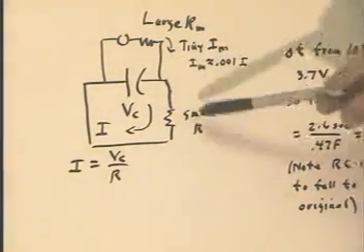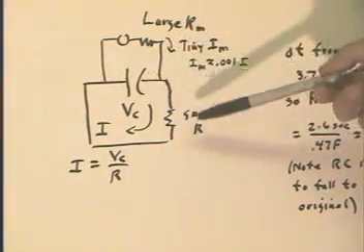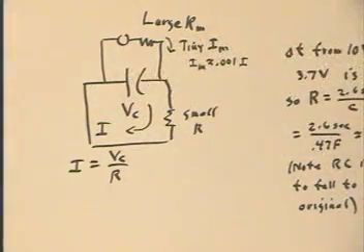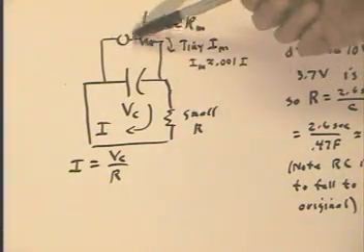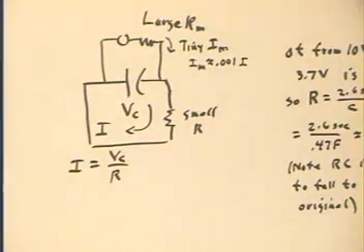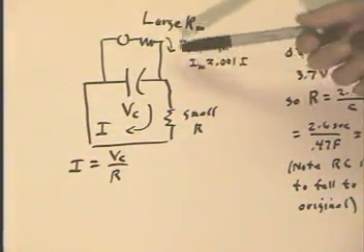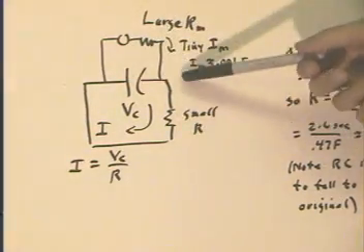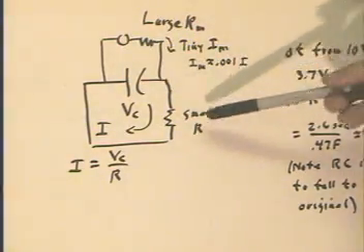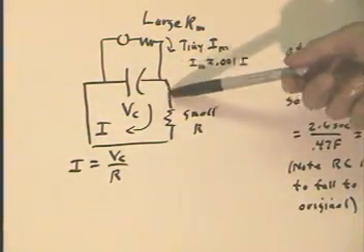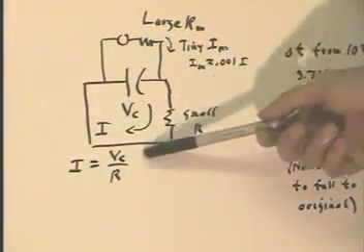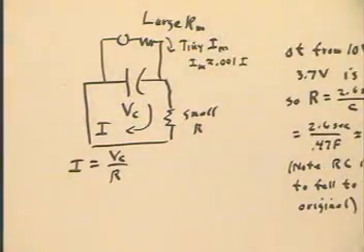That's assuming that we have a resistance of about the resistance of the generator on the order of 20 ohms or something like that. And the resistance that we measure in the meter turns out to be around 50,000 ohms, so it's even less than 1,000th the resistance here that we have here, so that the current here will be less than 1,000th of the current that we have here. In this case, the capacitor discharges through this resistor.